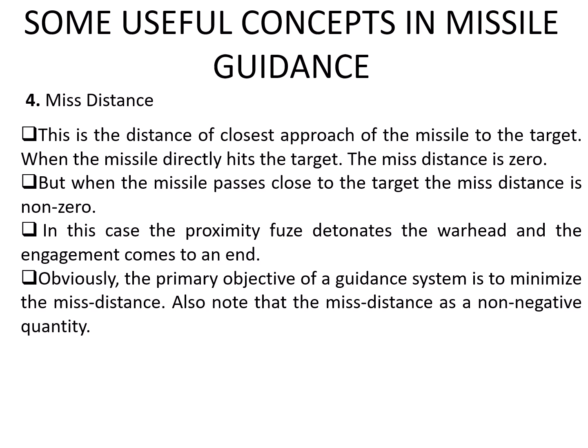Another is the miss distance. This is not the distance by which you are missing the target, but the distance of the closest approach of the missile to the target. We need to specify when your warhead will be exploded. It is not always that your missile will hit the target and then your warhead will explode, but we need to finalize some distance, such that at that proximity your warhead will explode. So that is defined by the miss distance. This is the minimum distance of approach.